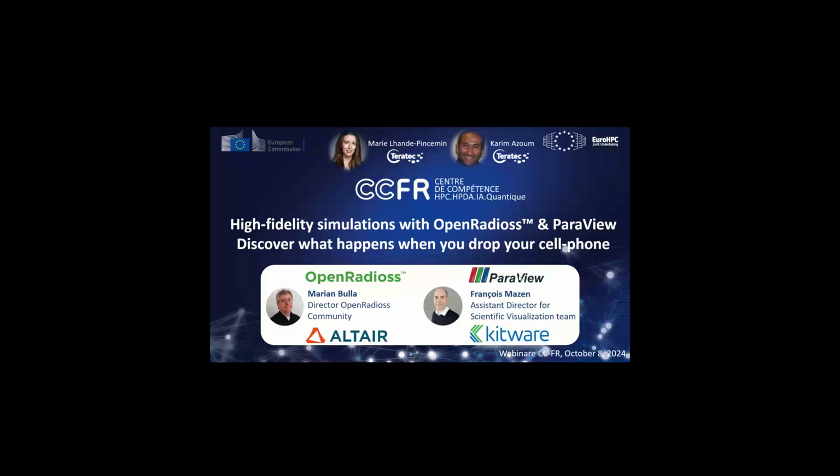We have another question from Atta. Can RAD files work with ParaView? So a RAD file is the input for the OpenRadioss solver, if I'm correct. So no, ParaView cannot open a RAD file directly. You have to simulate and generate some output files.